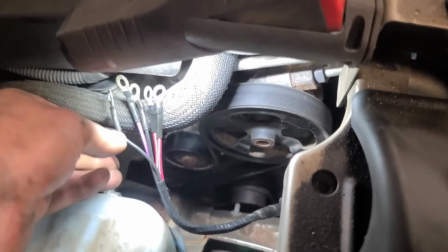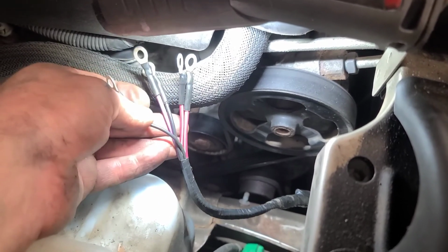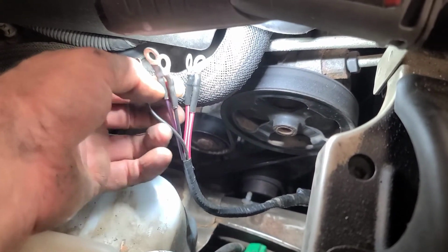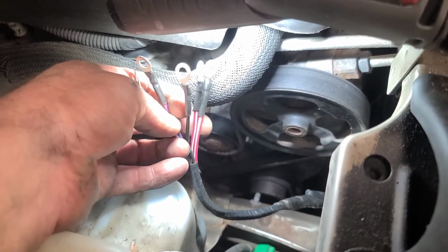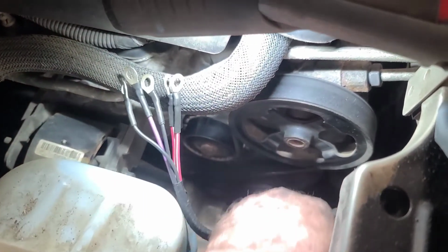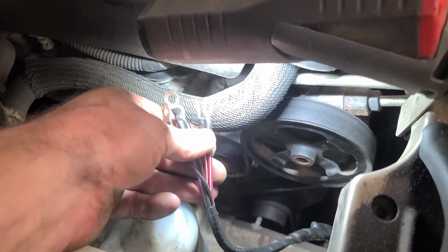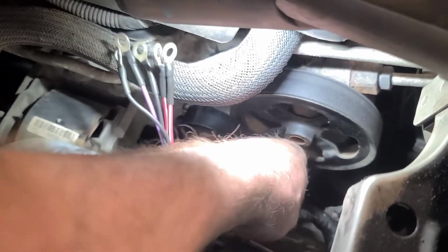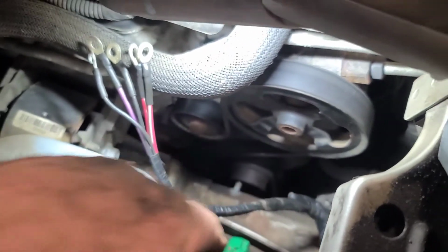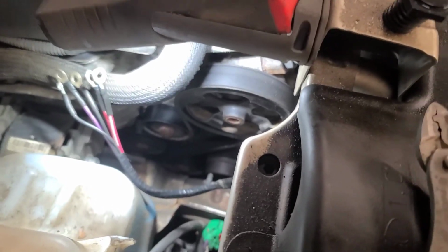So there's all the wires spliced together. I did double up 2 of the smaller grounds. These 2 black ones are going to 2 smaller grounds, but I kept the single heavy grounds individual. I put 5 terminals, 5 wires instead of the 7, and I've sealed it up as best I can, and we're going to clean up that stud and then bolt it back up and see if everything works now.